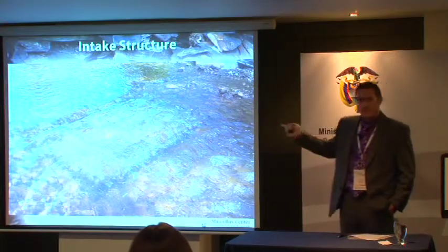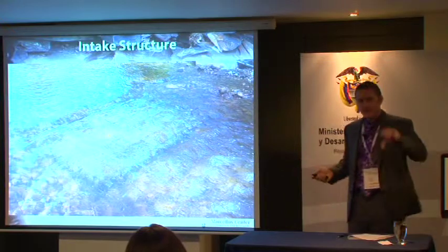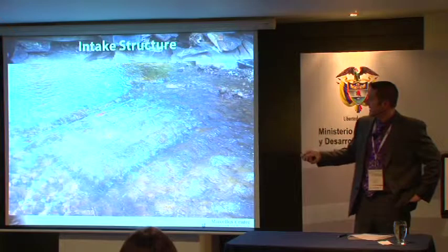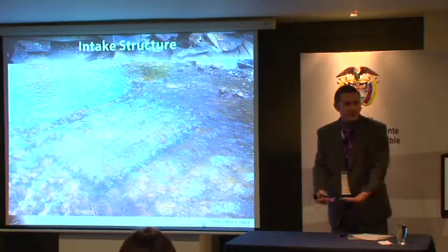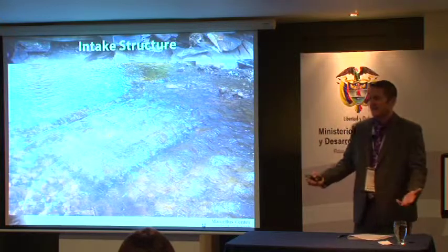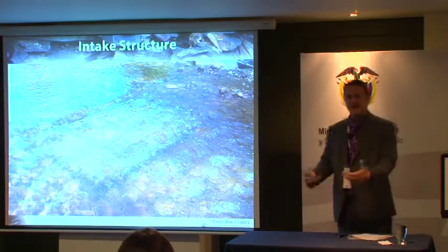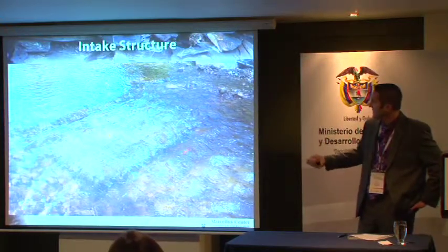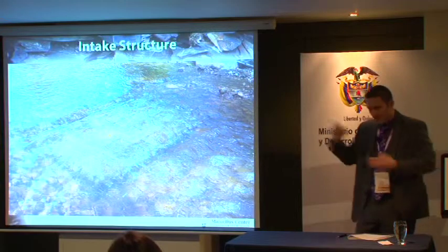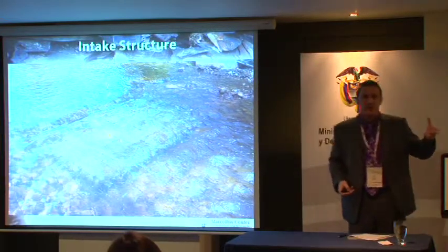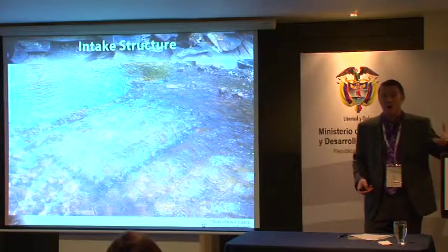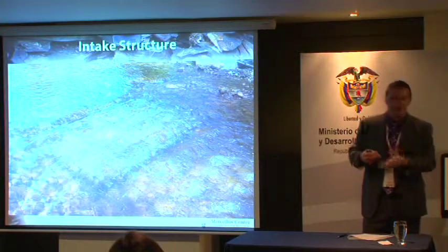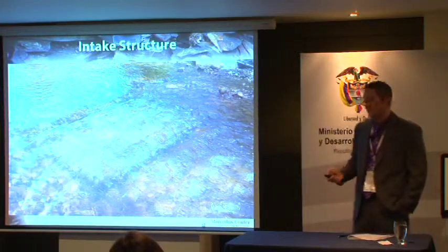This is actually one of the more unique intake structures. So sometimes you'll just have basically a pump in the creek, or you might actually build the intake so it forms part of the creek stream bed bottom, so it's less obstructive. So there's less of a hazard associated with it. You can kind of see there's a grate in here built into the stream, and the water actually flows down through that. And it also somewhat helps maintain the water quality. You don't get as much suspended solids. The water won't be as cloudy because it kind of naturally filters through the stream bed.